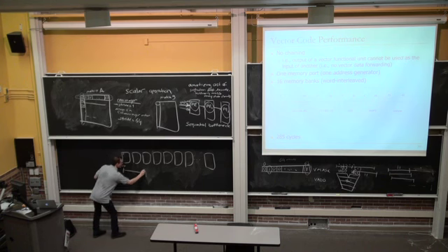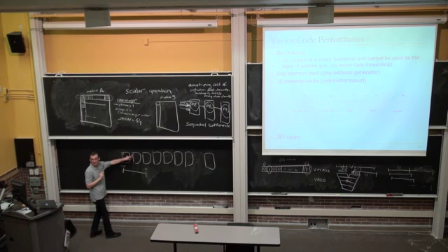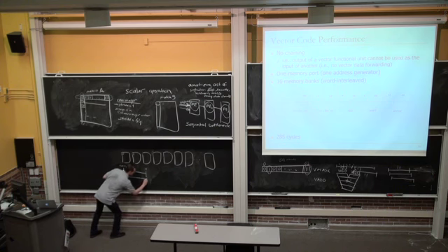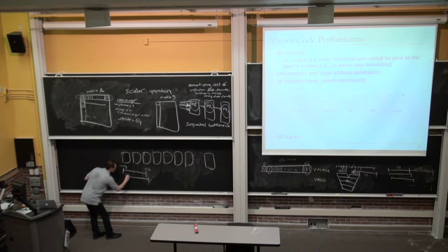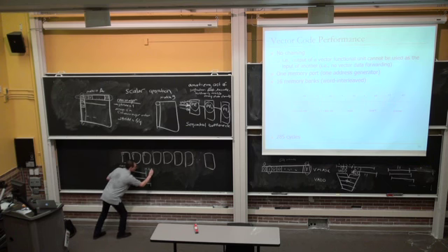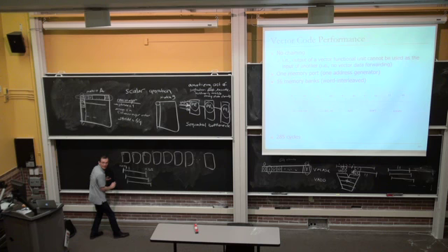The next element is in the second bank, so you can start that in cycle 1. This is going to take again 11 cycles and finish at 12. The next access is to bank 2. You can start that in cycle 2, and again, it's going to take 11 cycles, so it's going to finish at cycle 13.